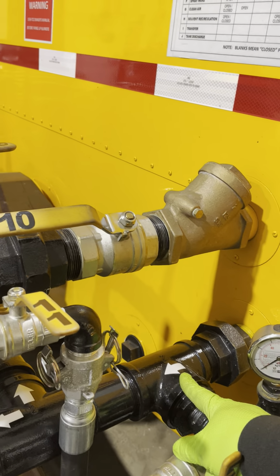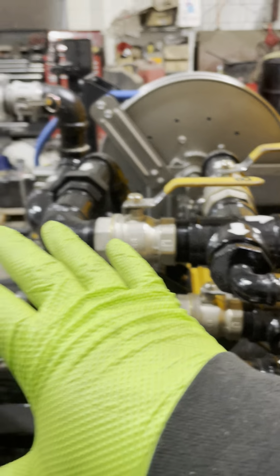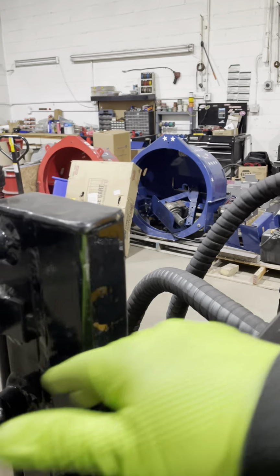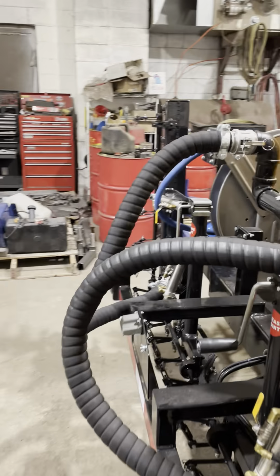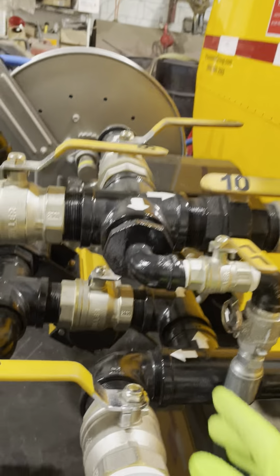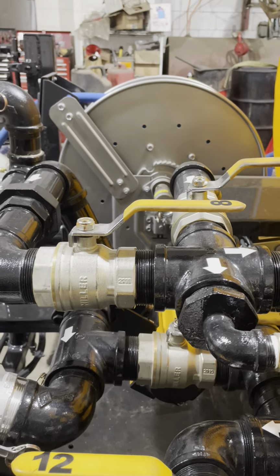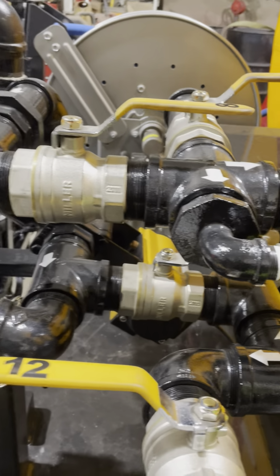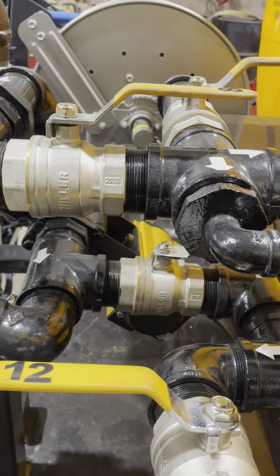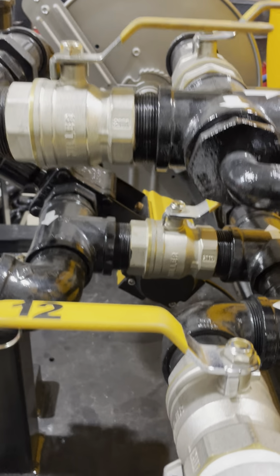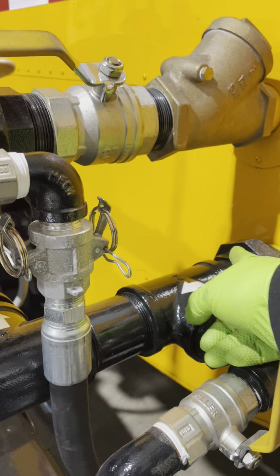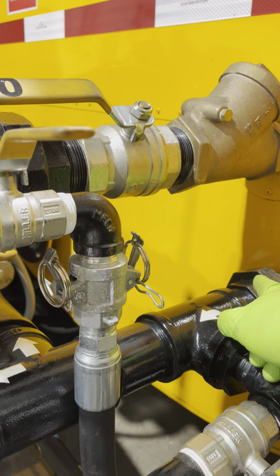So if we want all the material that's in all this plumbing and this manifold and in this hose and in the spray bar, gallons of material that this holds, all we're going to do is open up 6, we're going to open up 8, we're going to open up 10, and all that clean air is going to follow the same route as the material did when we were recirculating material. It's just we're not recirculating material now, we're recirculating air. We're pushing all the material back into the tank.